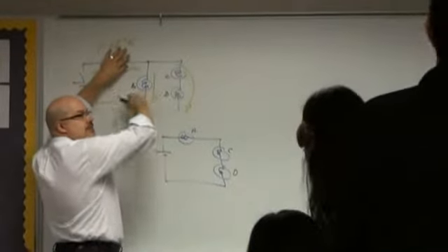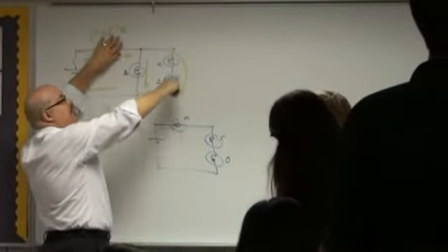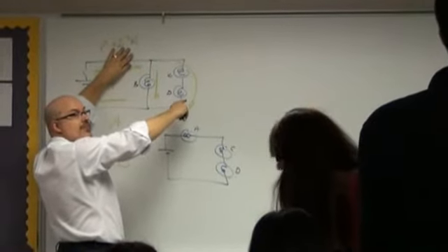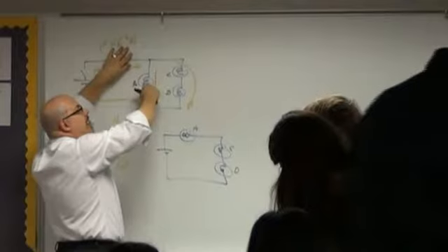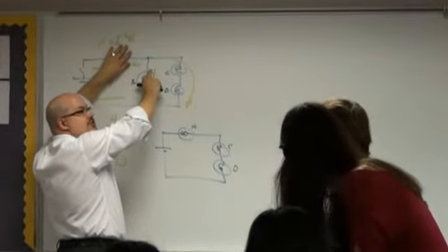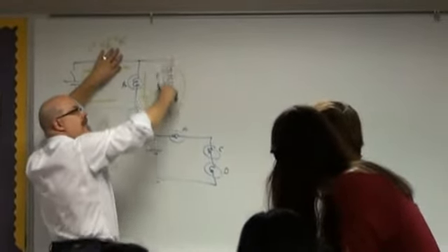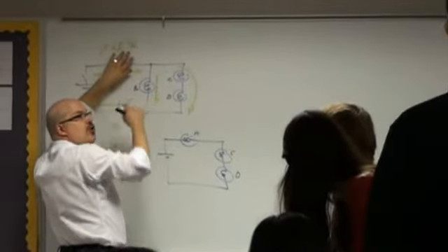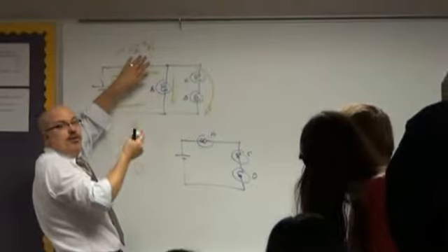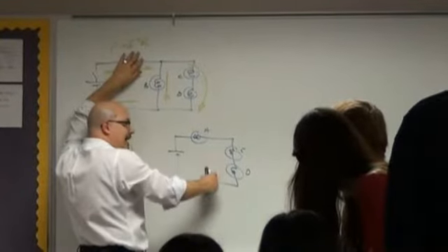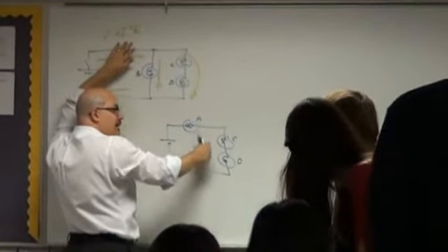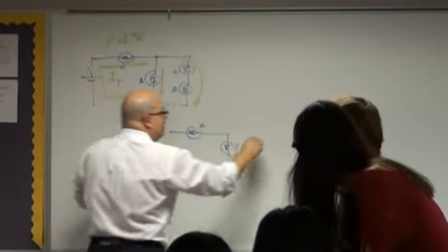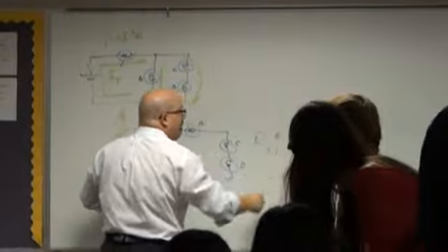All right, but keep in mind, net resistance. Look right here, everybody. When you have this in parallel with this set, whenever you add a parallel line, you lower the overall resistance of the circuit, right? So when I take this line out, there's less places for that current to go around, right? So therefore, the overall resistance total of the circuit has gone up.